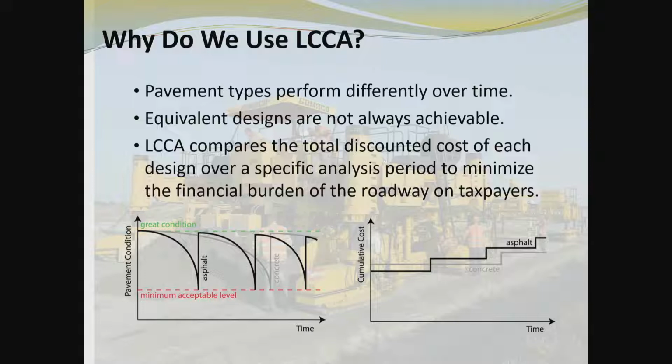If you go into an urban area, Chicago, Dallas, Fort Worth, any of the major cities would have a preponderance of concrete pavements. The reason is because that gap is huge. If you throw user costs in at anything more than about a 5% rate, it predominates the calculations. In this spreadsheet, we don't even consider user costs because it is such a wildly variable number depending on the level of traffic.